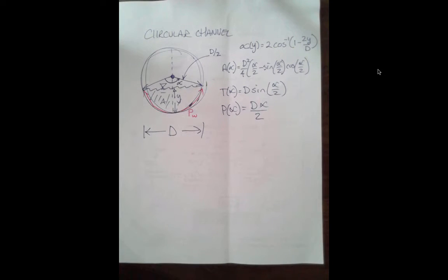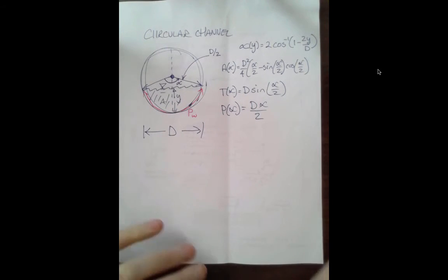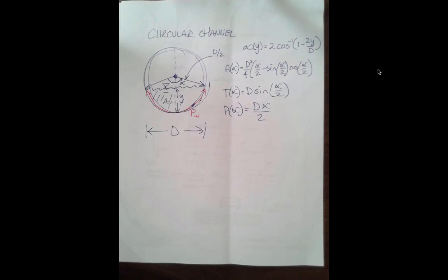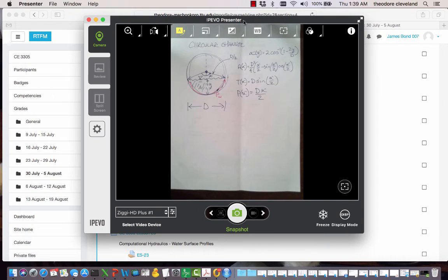Now, you notice in the trapezoid and the circle, I didn't bother to actually write the hydraulic radius. There's no advantage to trying to do the algebra to get into an algebraic form. In practice, we'll calculate an area, calculate a wetted perimeter, take their ratio, declare that the hydraulic radius, and then proceed forward. For doing these actual calculations, I've put together some online tools. I'm going to try to get to those and show you where they are.